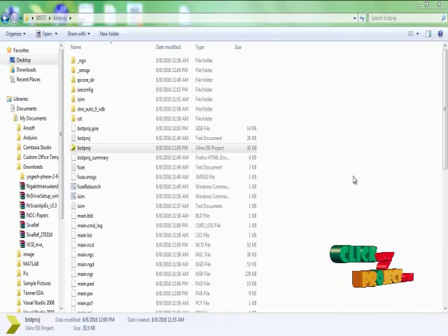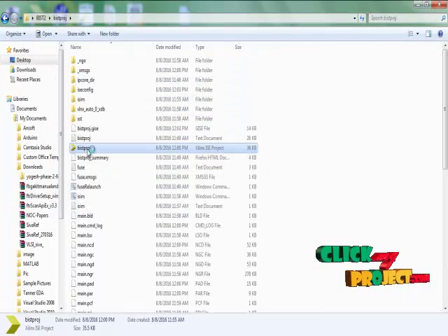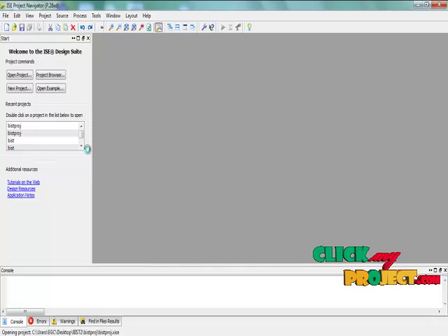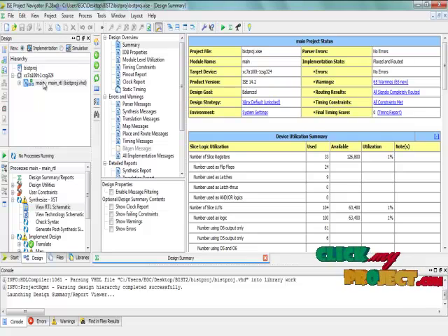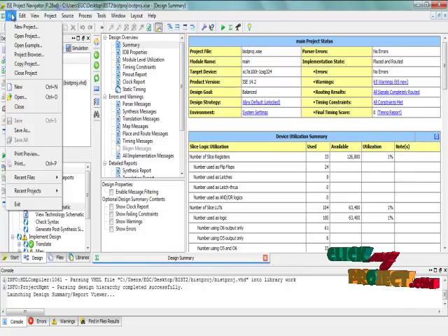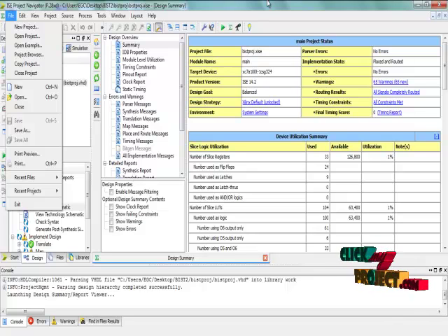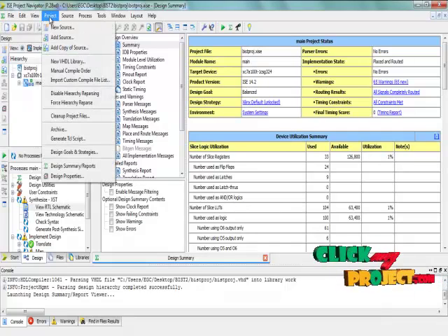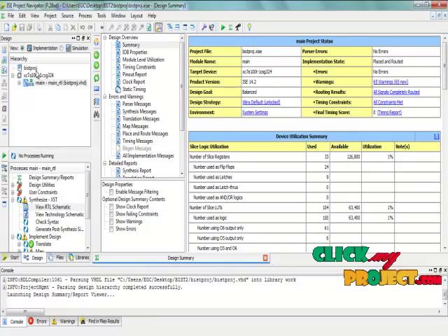Finally, we are going to see the output for our product. Click on the BIST project icon. We are using Xilinx 4.2 version for our project. So we have created the BIST project. For creating a new project, click on the File option and click on New Project and specify the path where you want to save the project. Then again click on Project, New Source for the program file. It will be created and the program file will be added to our project.